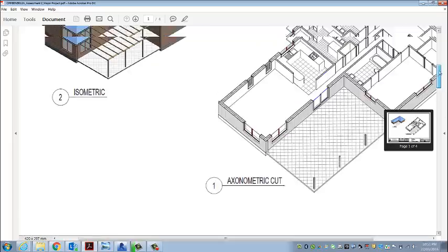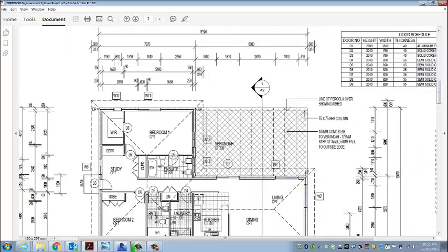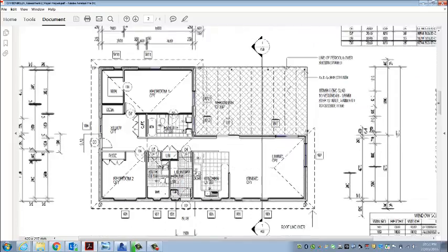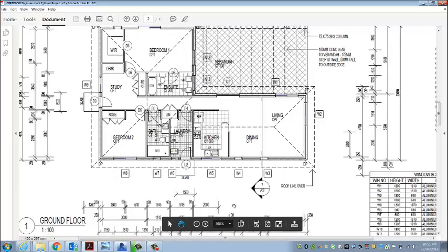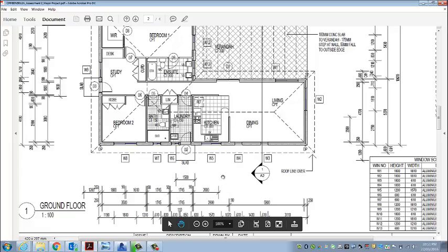So there it is up there. In the same way we'll work from the centre, working out this way, and from here working out that way. So it's important to follow that hierarchy of dimensions. It makes it easy to read. And I hope as you're working through this and trying to create your own rooms that you realise that and think about whether you think that works and whether that flow is helping you understand what it is it's dimensioning. And if it's not, maybe it needs a little bit more clarification again.